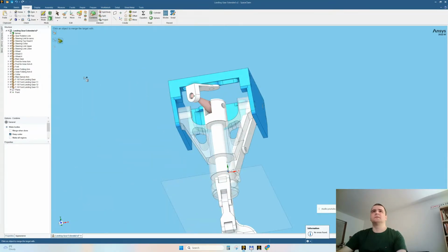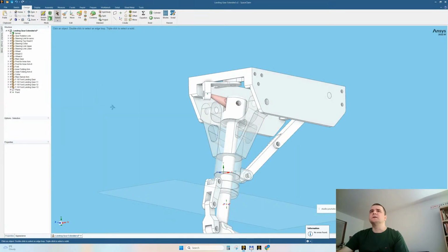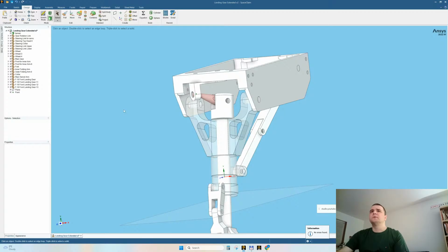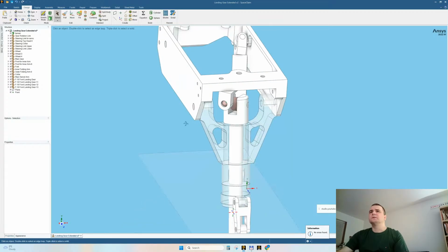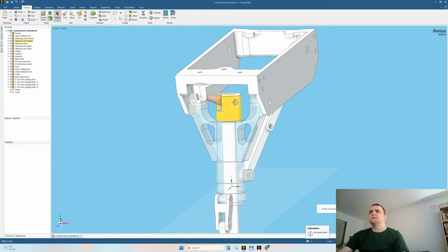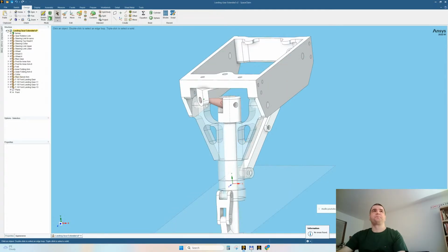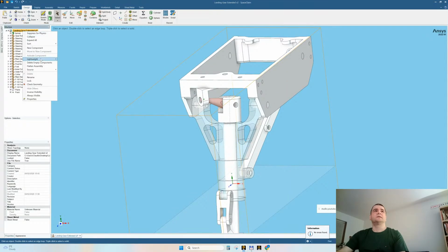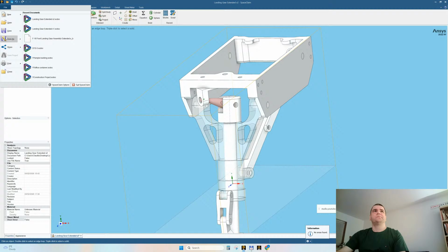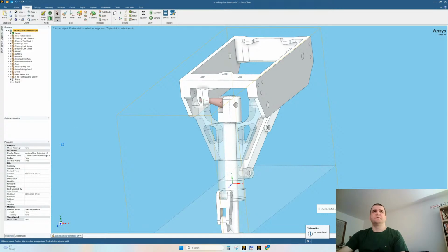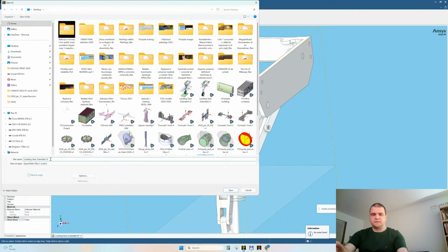We'll not fuse anything else. Escape. Then lots of joints. Right click, delete empty components. Right click, source, internalize all. And let's make version 3. Better safe than sorry.